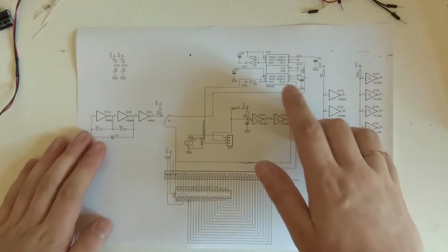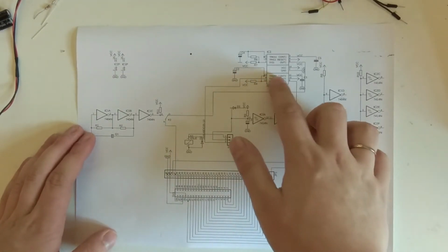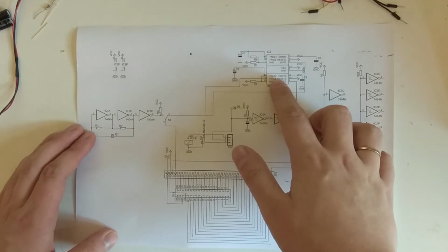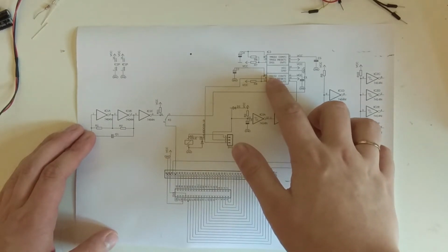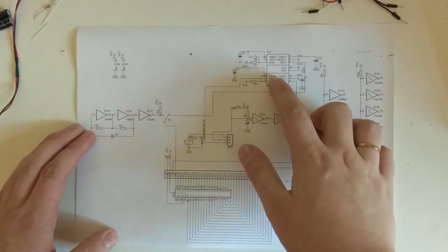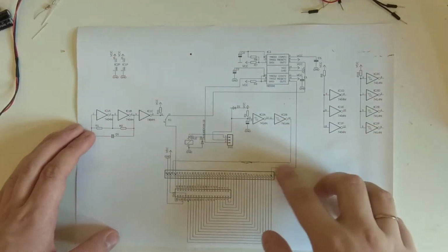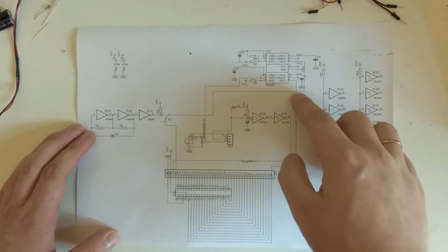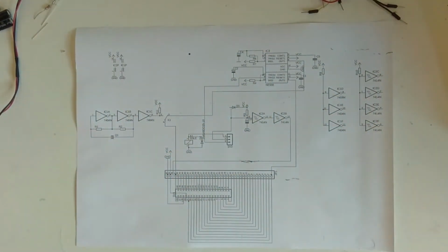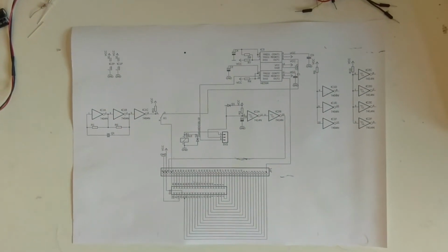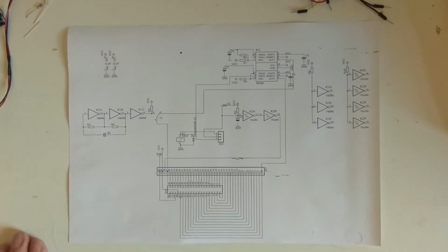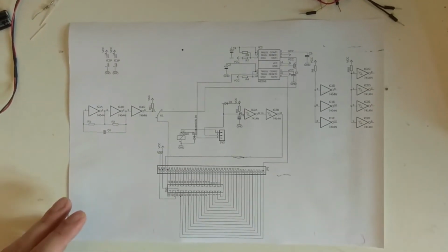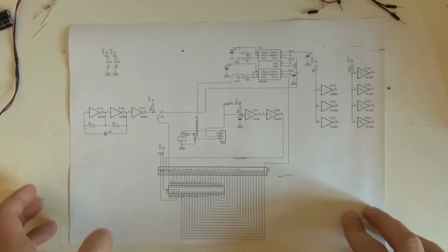And I've got the second 555 hooked up as a monostable, basically a one-shot. This is supposed to trigger the wait line, so when you're on the slow clock, you can just pull the wait line down on the Z80 and stop at the current instruction. But this is not working so great.